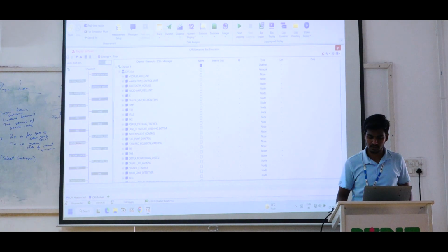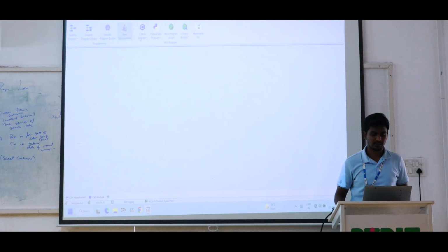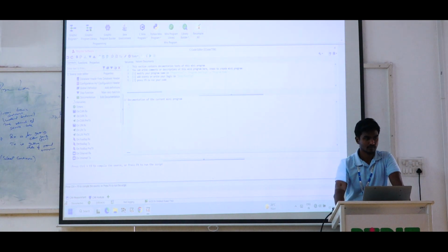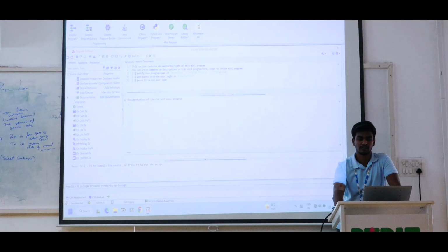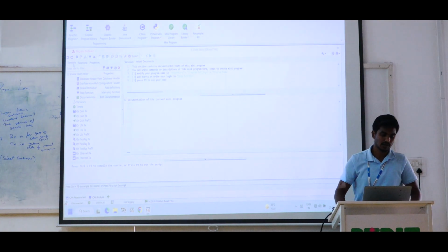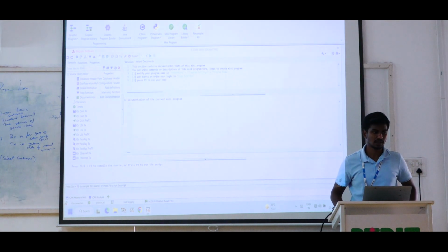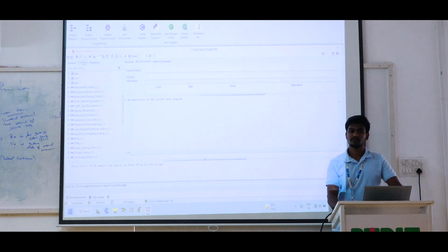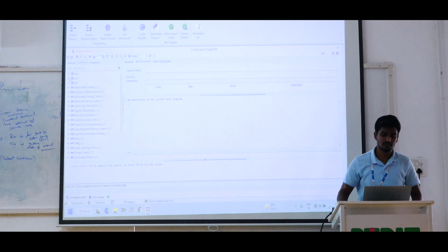So just close this RBS and open the CAPL script. Open our scripting. So go to functions. Initially you are working in the symbols column. In the top left you are having the three tabs: symbols, functions, and then properties. Please select the functions and then move forward to COM.